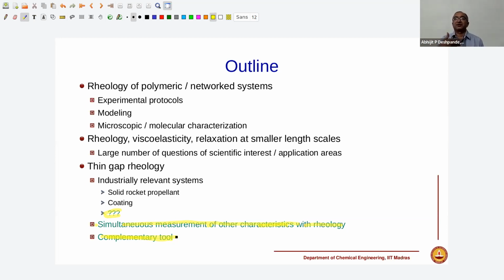But for metallic or ceramic materials, it's an order of magnitude less complicated because their response is small deformation and largely in the elastic domain. The key feature will depend on the resolution you can get through the AFM tip, which sets the smallest possible scale. Depending on what probe you use, you can go to slightly smaller or larger dimensions. All right, thank you.